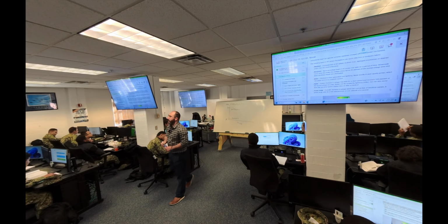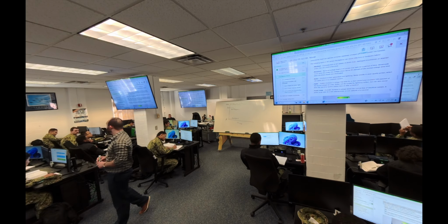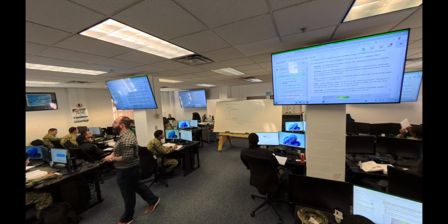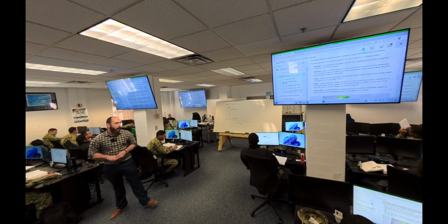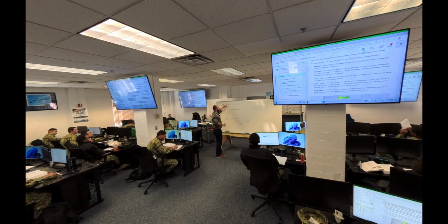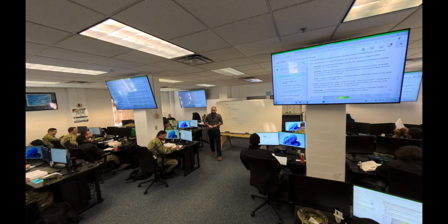A brownout is reduced power of AC, right, because that's what's coming from our commercial power, to below 80%. This could happen if systems are overloaded. It can't provide everybody the power, right? We add a bunch more buildings on base, and it's just too much, right? Not everybody can get the 100% they wanted. We're not operating at 100%. So brownout is less than 80%.